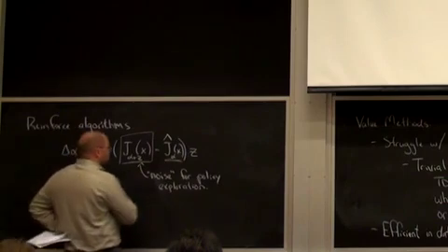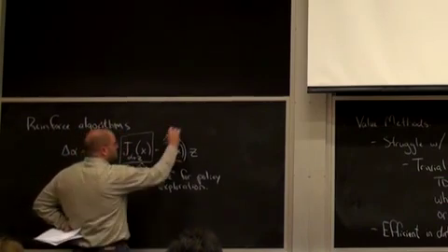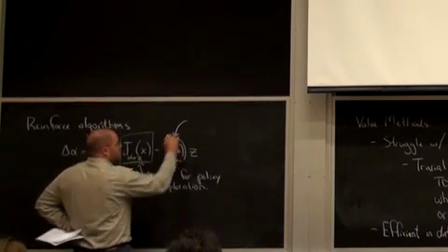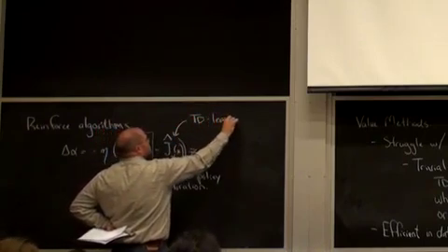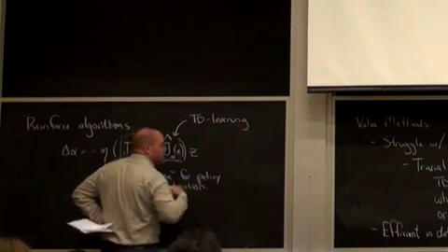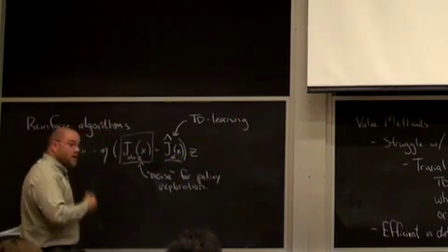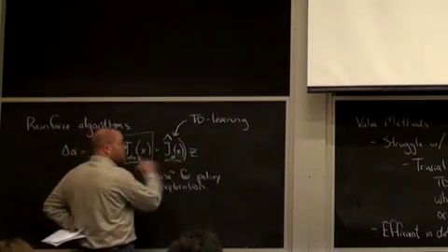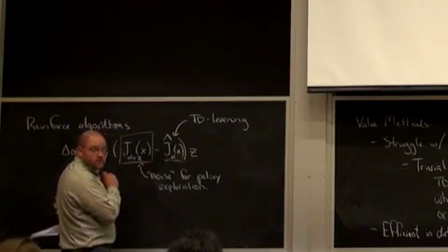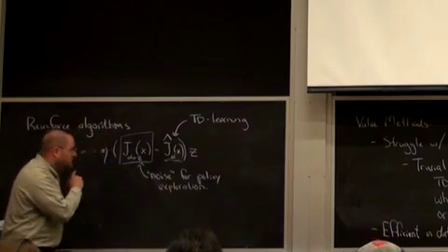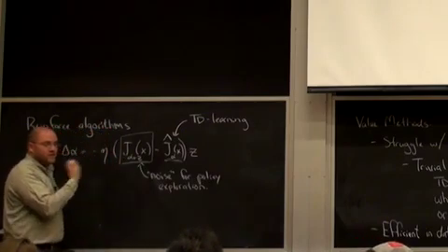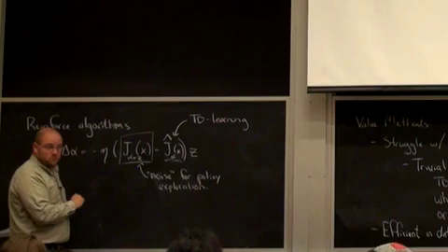So the simplest way to think about an Actor-critic algorithm is to go ahead and use a TD learning kind of algorithm. Every time I'm running my robot, work in the background on learning a value function of the system, and simply use that to compare the samples you get from your policy search.